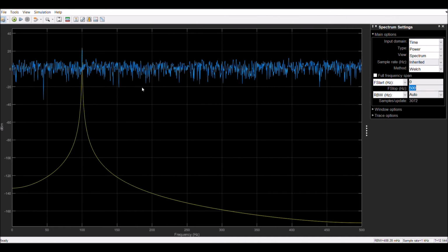So we look at the positive spectrum, and first, this yellow signal is the ideal signal. For our ideal sinusoid with no noise induced, we can see a pretty distinct peak here, and not really any content outside of that main frequency band. But for the blue signal, where we have noise imposed, we have a fairly high amount of noise. Although the peak of our main signal does still stand out at this noise level, it is harder to pick out clearly than with the yellow signal.